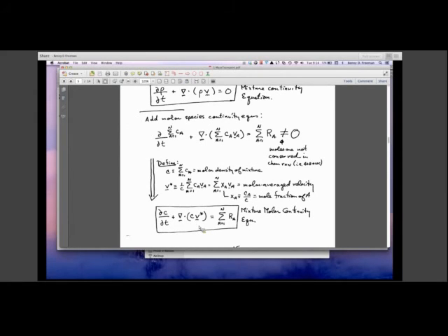The further step is to very carefully decide how we're going to apply boundary conditions. And I gave you some boundary conditions at the beginning of the course, and now I'm going to come back and derive those, show you where they come from. And then the fluxes that appear in these expressions, if they're driven by diffusion, we need constitutive equations for multi-component mixtures for those diffusion expressions.